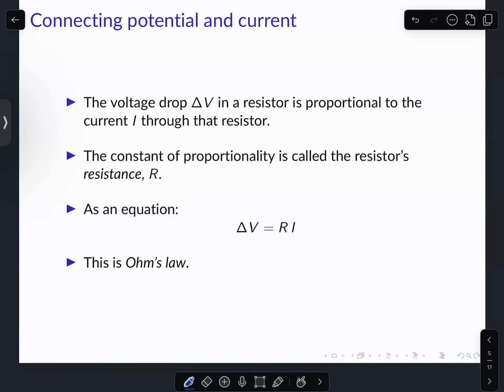Note, by the way, that to say voltage and current are proportional, the voltage drop in a resistor is proportional to current, means that even if you've got an itsy teensy bitsy little voltage, that will drive some current through a resistor. It's a common mistake for beginners to think that resistors block voltage.